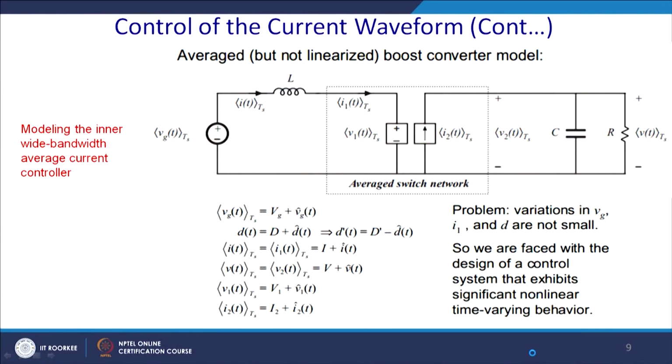Since the system is non-linear, you have switching, on and off states, so we give a perturbation in and around, very close to the operating point. Then we see how this system will behave, and this is called average modeling. By average modeling we can capture the phenomena and stabilities which are 1/10 of the switching frequency.